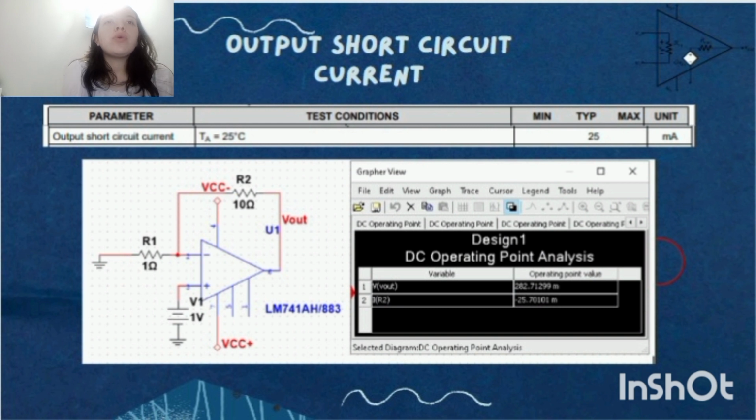However, if a short circuit occurs in the load, for example, if the leads touch or if two terminals of the load are accidentally connected, the resistance of the load is reduced to 0 ohms, resulting in a short circuit and an extremely high current flowing through the output stage of the amplifier.